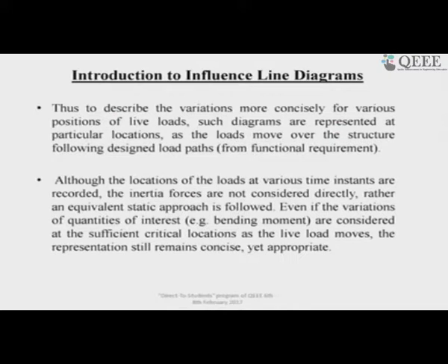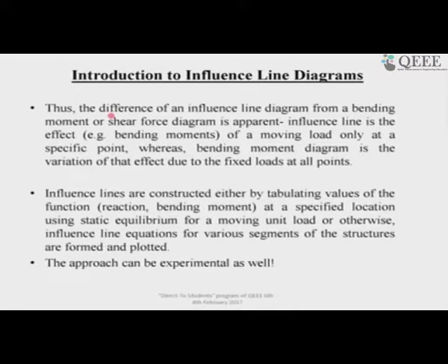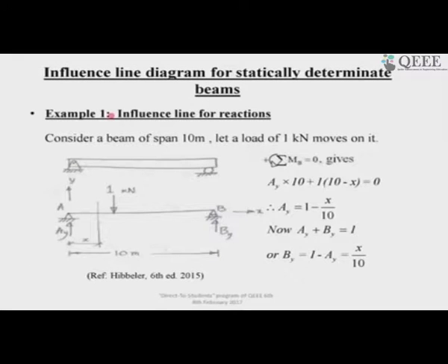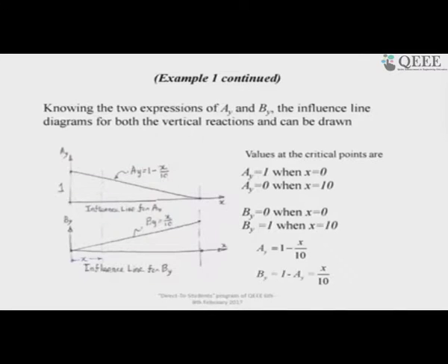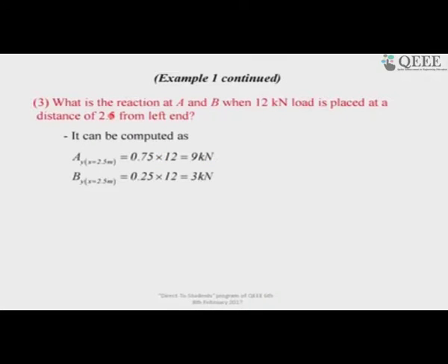So then we have also shown on the first day the actual construction of the influence line diagram for different effects for a beam. We have drawn the influence line for reaction, and also we have understood how useful the influence line is to determine where the effect is the maximum, and also to determine the effect at a particular point or section, and then also the load when it is given anywhere, we can determine both the reactions immediately.